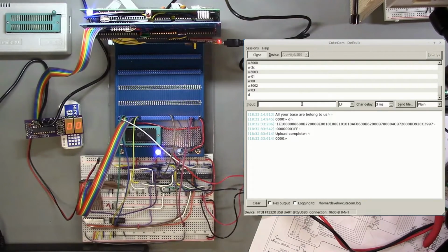So if we run the test program, let's set the monitor address to hex 1000, and then the S command invokes the current address as a subroutine, so that will call the entry point of the test program. And so in theory, what has happened is that the VIRQ tab table of IRQ handler routines has now been patched so that IRQ3, when it is received, now calls the test IRQ3 handler in the test program.